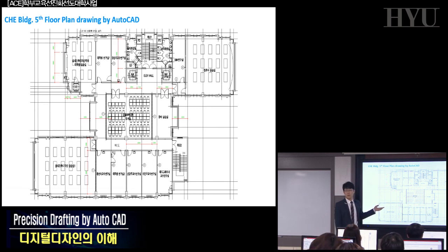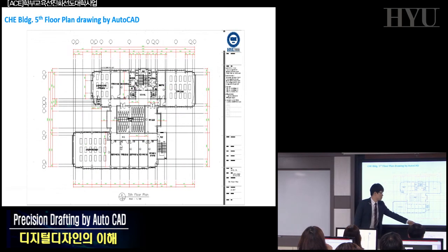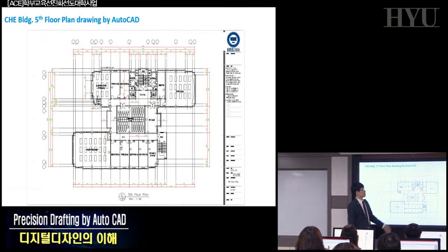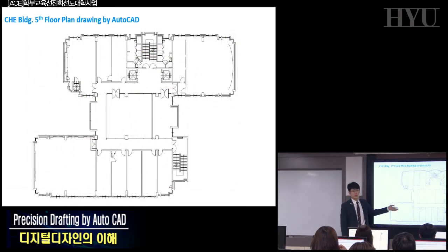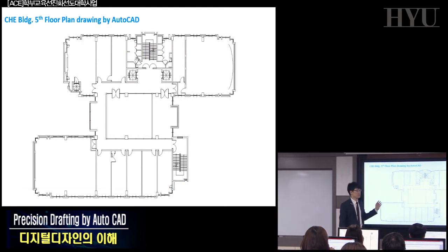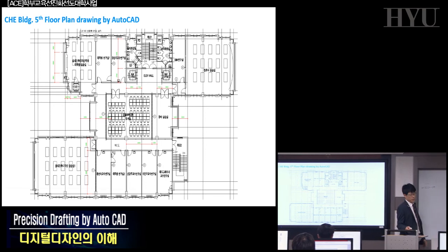This is the highest level of detail floor plan for the actual remodel of this building last year, okay? You don't need to put the frame or this kind of title legend or technical notes. Just focus on architectural elements, exterior walls, interior walls, doors, and so on. You can simplify, but you have to draw precisely according to actual dimension, okay? Which means the length between those two areas is 7.2 meters, something like that. You have to follow that dimension, proportion.